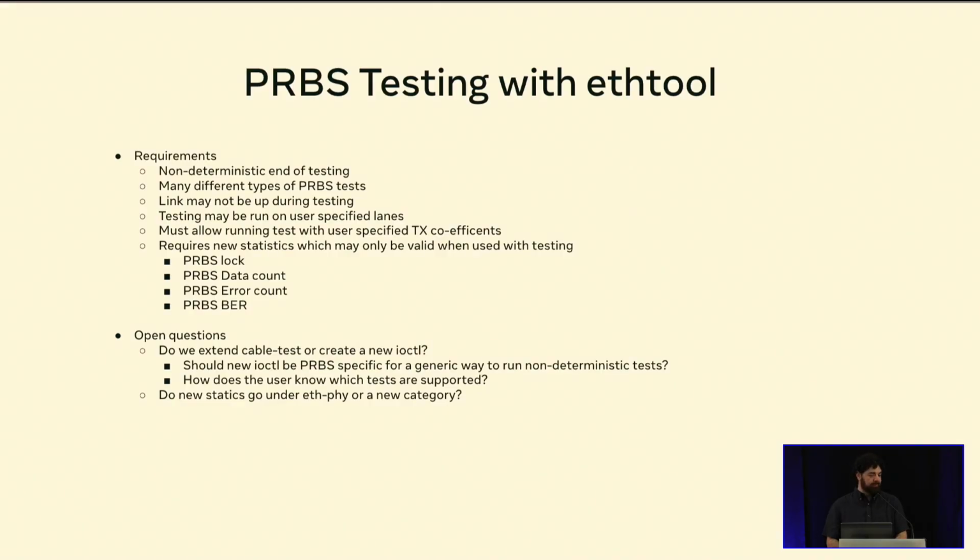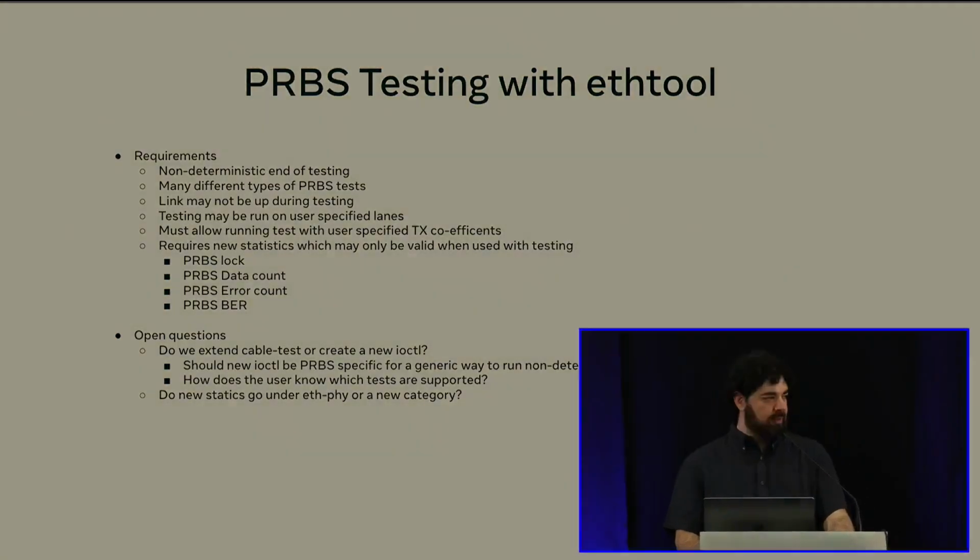Okay. So what I wanted to say is that there already exist a few drivers for PHYs, especially SerDes PHYs, but they are not located in drivers/net/phy, but rather drivers/phy. This is a generic PHY subsystem that handles SerDes lanes. If you look at this class of drivers, they are for Qualcomm, Mellanox, Marvell. They already seem to have some PRBS support, at least at the hardware level, but no interface to use that. So these drivers are used by the net stack, but they are not really part of the drivers/net/phy subsystem, but rather the SerDes subsystem.